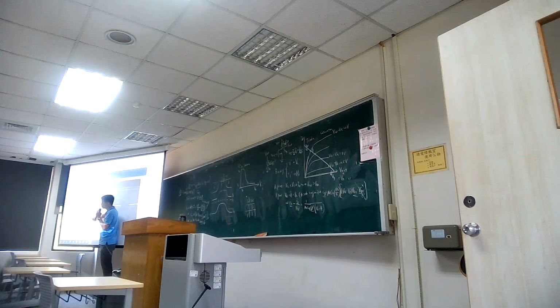Okay, so we try to increase the voltage along this power supply and see how much current we can measure at the drain side. If you compare these two cases, in the top one the voltage at the gate side is 0.7, and in the bottom one the gate voltage is 1 volt. You can see the drain current is 4 microamp, and here it is 10 microamp. We increase the voltage, the current increases, which is proportional to VGS minus VT. So remember that compared with the saturation current, in most cases the current is not as strong.